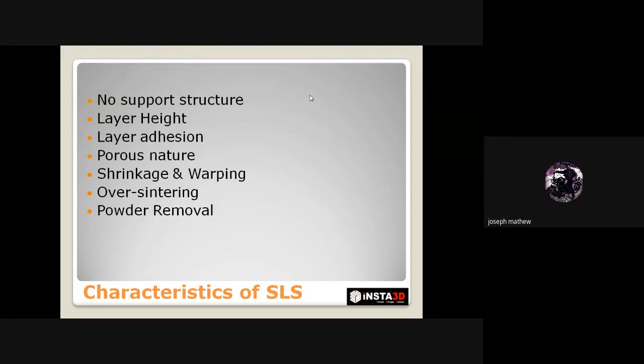So, for example, a 0.5 mm wide slot or a hole with 1 mm diameter will successfully print on a 2 mm thick wall. Whereas if we keep a wall thickness as 4 mm, in order to print a 0.5 mm wide slot or a 1 mm diameter hole, it will not print successfully in an SLS 3D printer. So these kinds of design characteristics have to be studied before entering into the SLS technology.